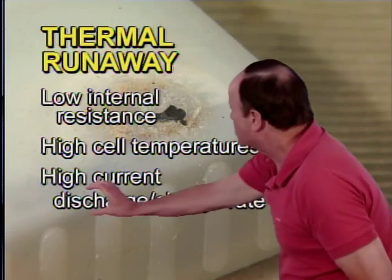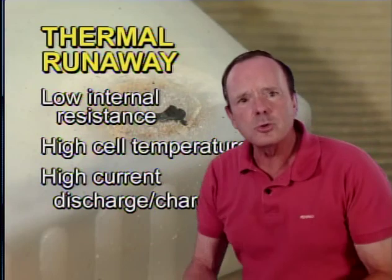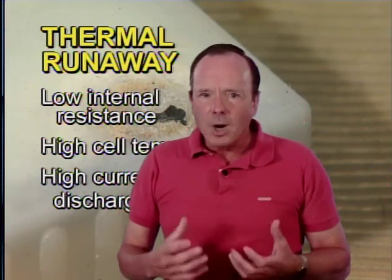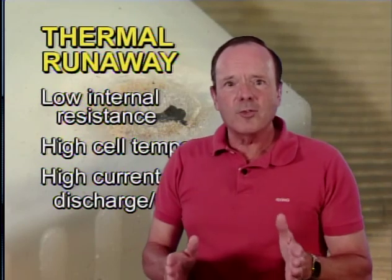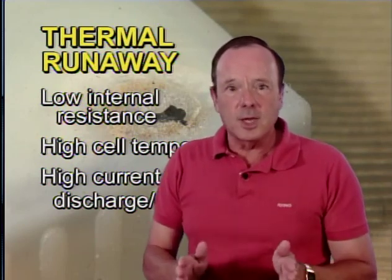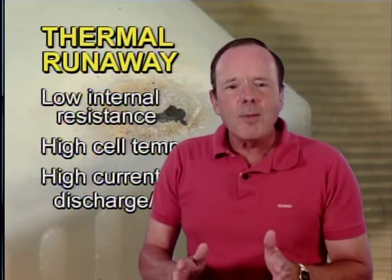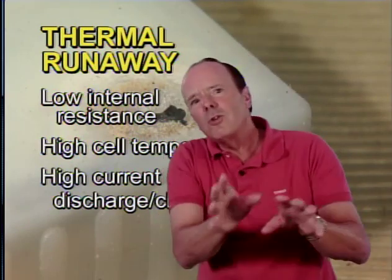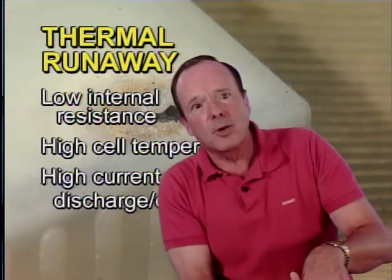First of all, it discharges very quickly, and that tends to heat it up and start this cycle, but it also charges very quickly. One of the reasons it charges very quickly is that we have generators in aircraft that put out a constant voltage. That's called a constant potential charging system. What that means is when the battery is very discharged, it charges up very rapidly, and that tends to heat the battery even further.